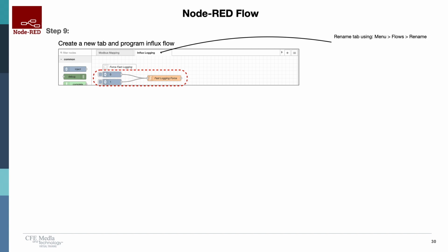In this example, when the machine is running, we would want a much higher frequency of data collection versus when the machine is just sitting idle, waiting for the next production to be run on it. So that's what we're going to be doing here: controlling when we're injecting data into Influx. And this builds a little more intelligence into the application that oftentimes isn't available on a SCADA system even.